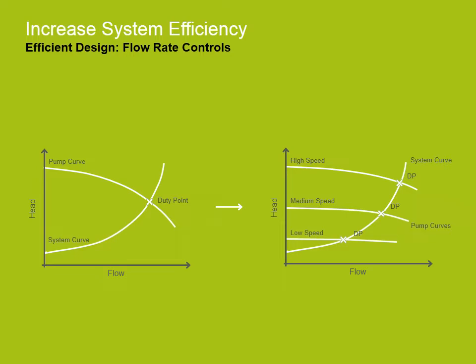By reducing the pump's rotational speed to match the demand of the system, less energy is required to run the pump. As you can see on the right, the more settings, depicted by the pump curves, the closer the pump is able to operate to its best efficiency point. However, in the instance that a pump naturally operates close to its BEP, little savings are actually achievable, as VSD pumps operate with less efficiency than traditional pumps and generally reduce the lifespan of the pump.